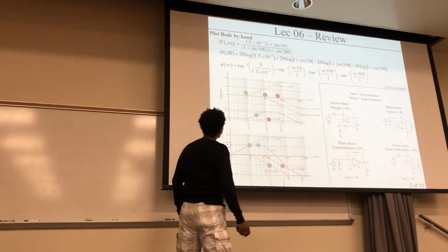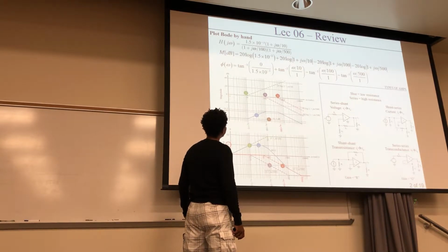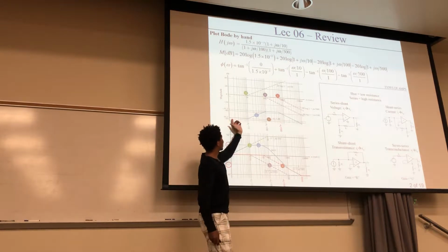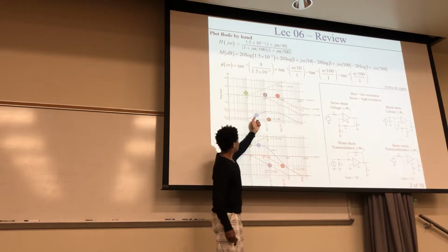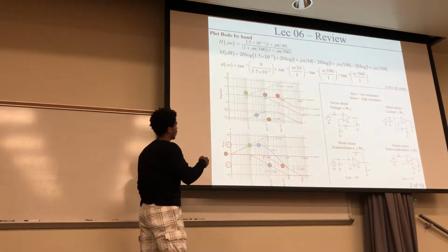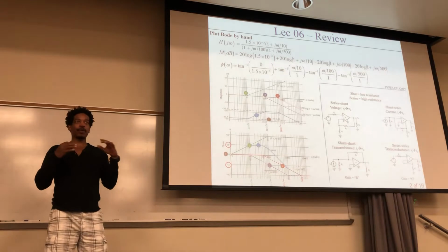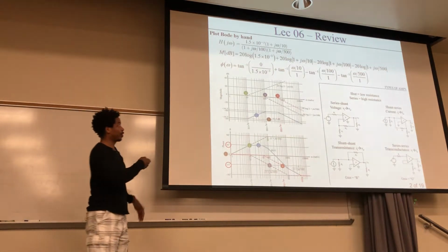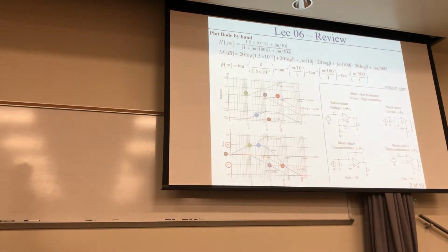Magnitudes. Here's what I'm thinking. If you were given a blue curve like that, you would have to think, what kind of lines are there? First they're straight, and then either they go up at 20 decibels per decade or down 20 decibels per decade. What kind of ways would I be able to generate that using just those things? Can you guys see it now? Can anyone not see that? Okay, good. That would be the quiz question.